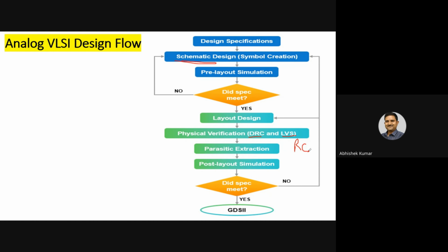In electronics you must know words like mutual inductance, mutual capacitance, crosstalk. Whenever two parallel lines are close to each other, unwanted capacitance will be added. Those are the parasitics.